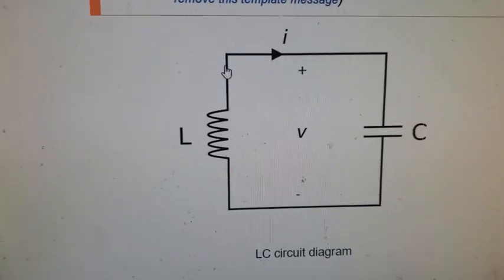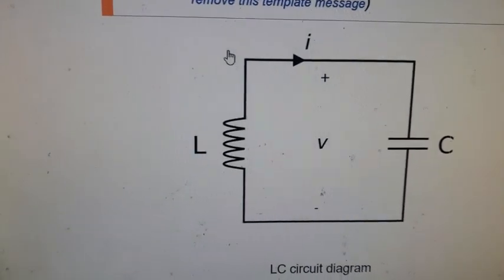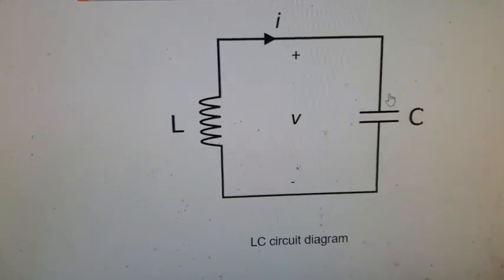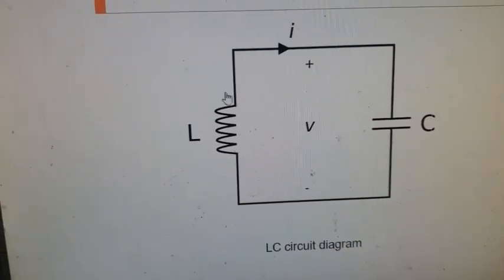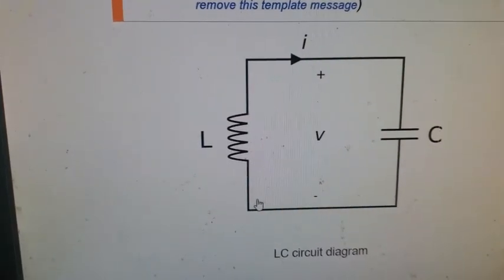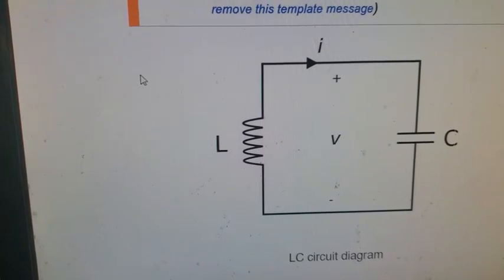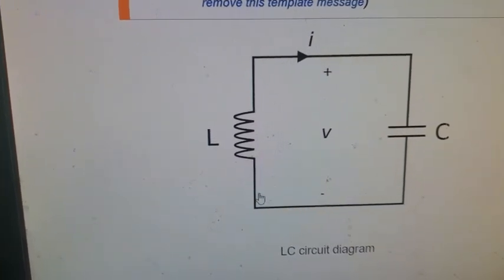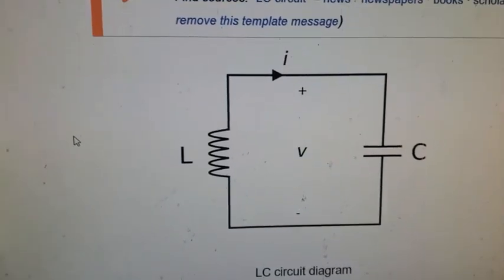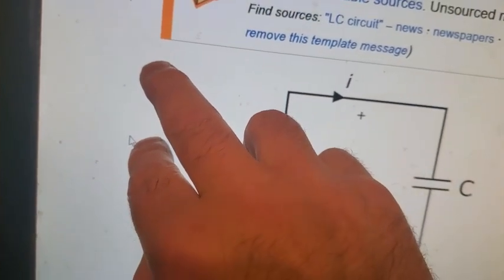So the last thing I want to talk about, and then again we'll fire something up. If you have a backwards diode coming off of the positive here, going out to another cap with another line going to this positive, going to the negative of another cap, and then another line going out here. Now you have a buck boost converter, so that when you discharge this, you see voltage show up here.